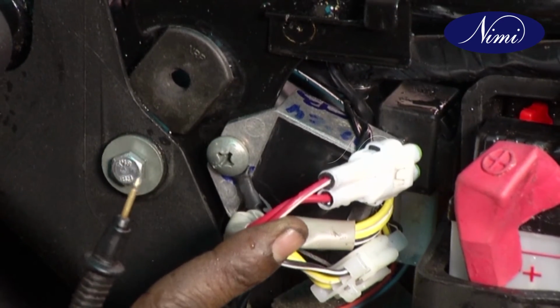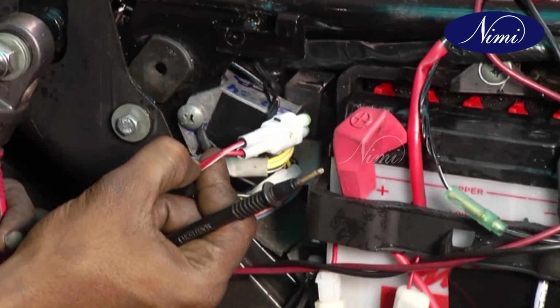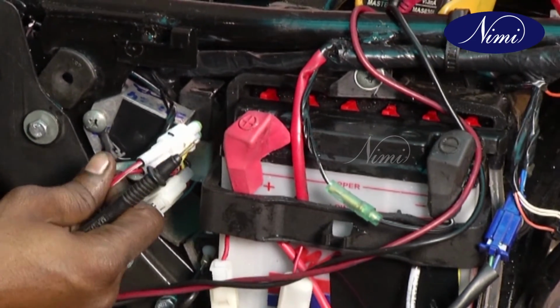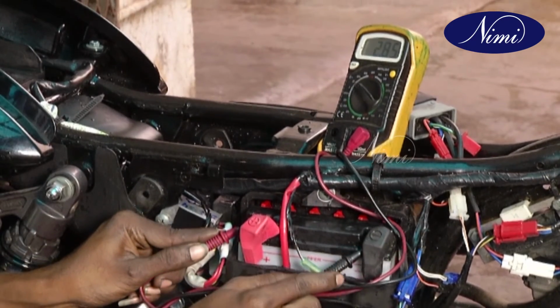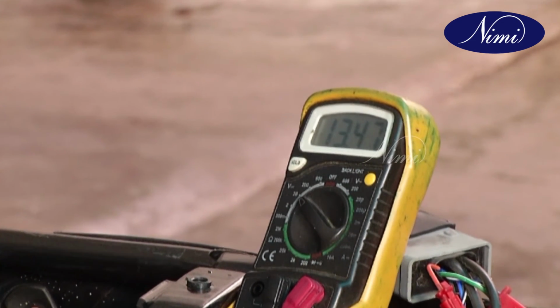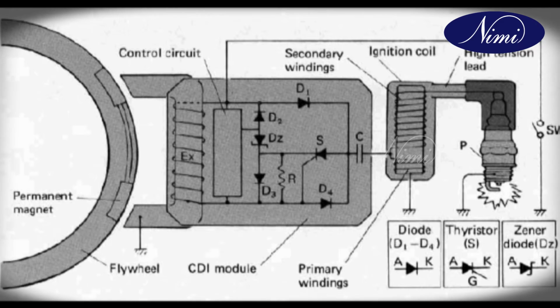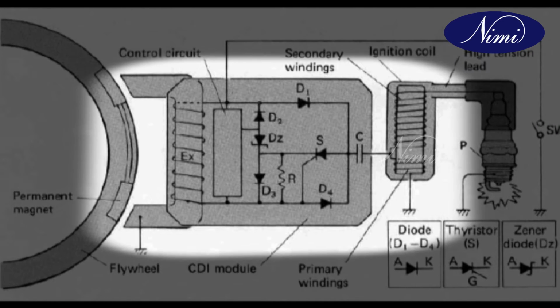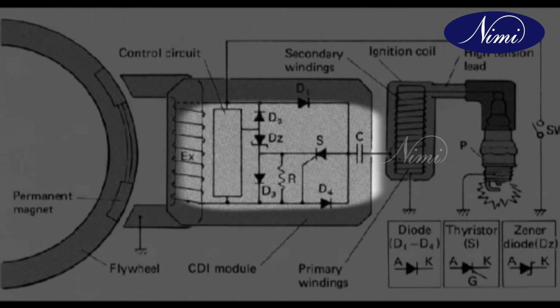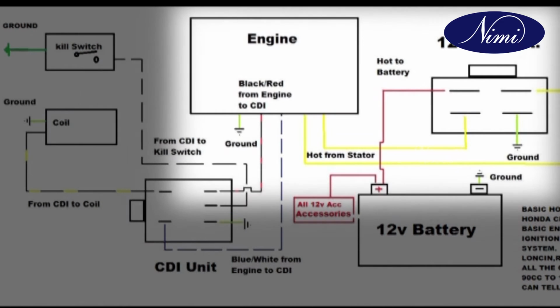Check the connectivity between voltage regulator, charging rectifier and diode system and the battery. Ensure that the battery is not overcharged or undercharged. Check the diodes using diode check function. Diodes are frequently used in the wiring harness to provide circuit insulation. Check the resistance between voltage regulator and magneto assembly using a correct range of ohm meter.